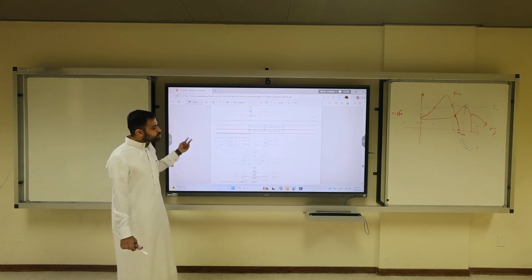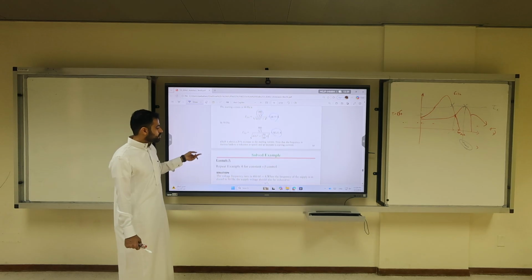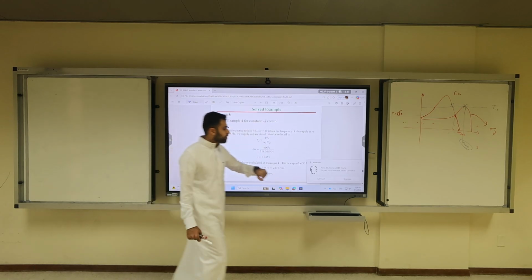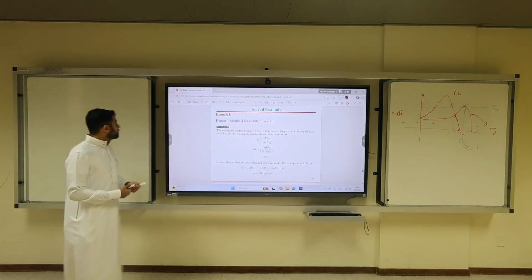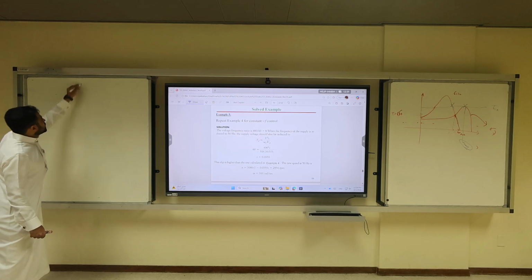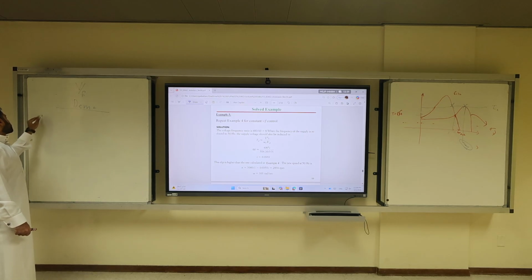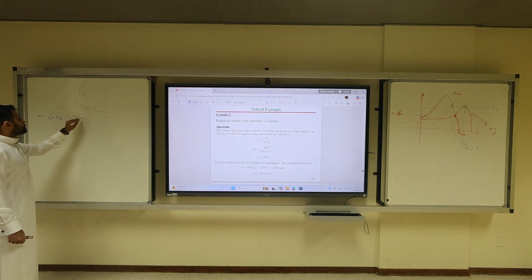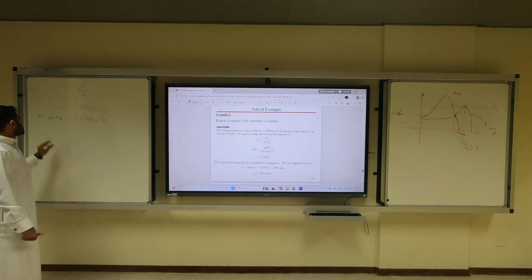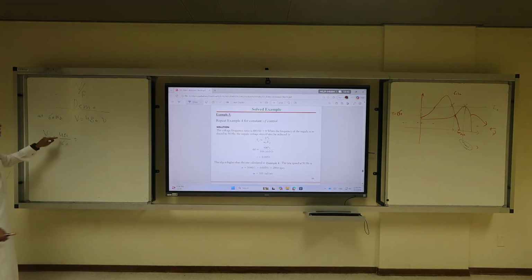So this is a very bad or huge number, and try to do these calculations yourself, okay? The last example is, let's do V over F and see what will happen. This is the V over F demo. It's very easy. At 60 Hertz, what is V? 480, line to line. So what is your V over F? 480 over 60. What's this ratio? 48 divided by 6 is 8. So your V over F is 8. You go to 50 hertz, V over F is 8.